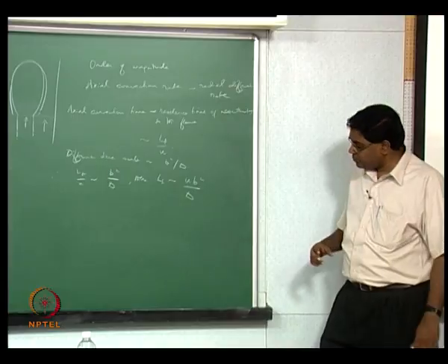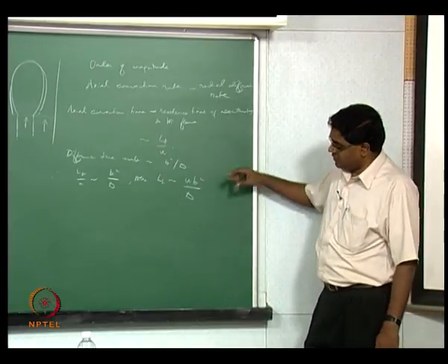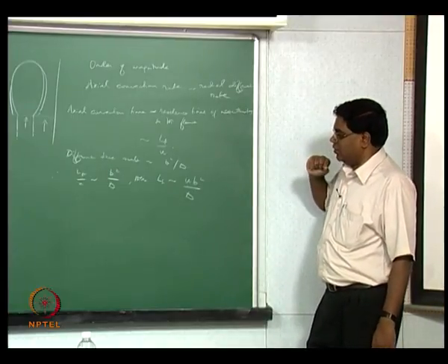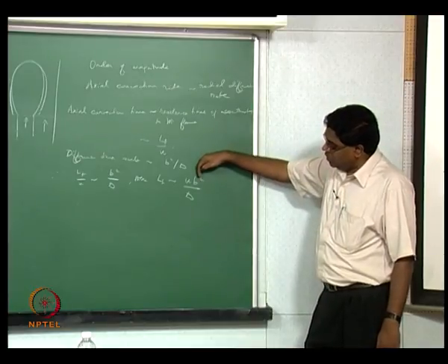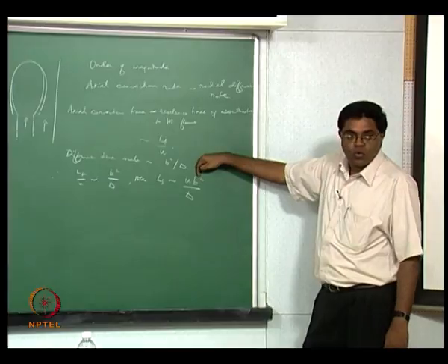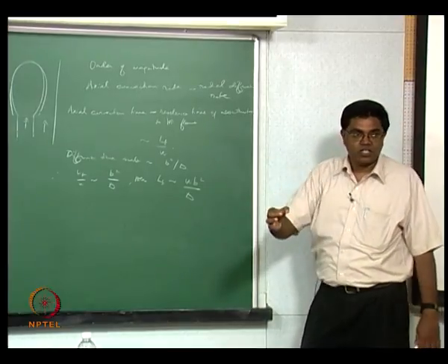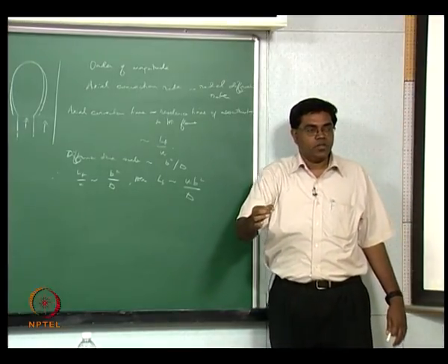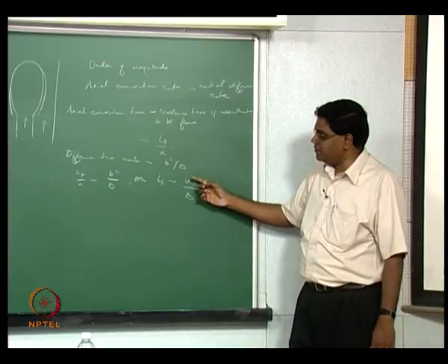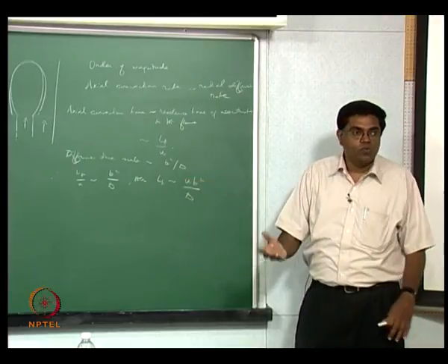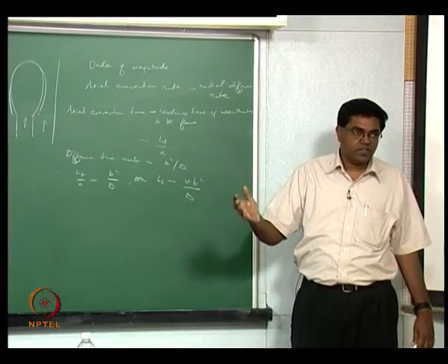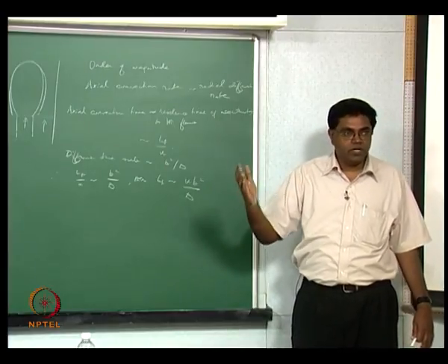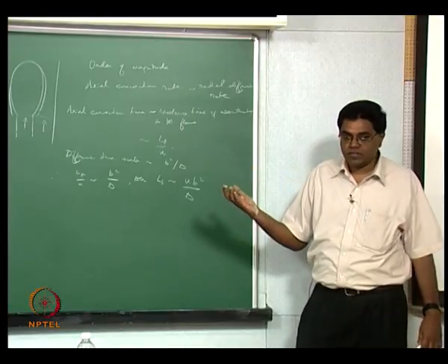That's fine. Now what that means is there are two things you can look at. One, the diameter squared is proportional to the cross sectional area, and the cross sectional area times velocity is essentially the volume flow rate, like what you would measure with a flow meter, let's say, in liters per minute or meters cubed per minute or whatever it is, right.